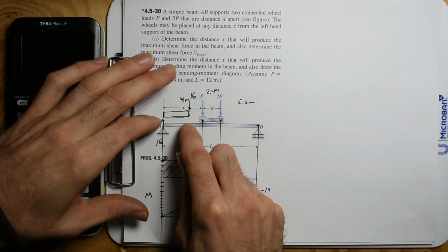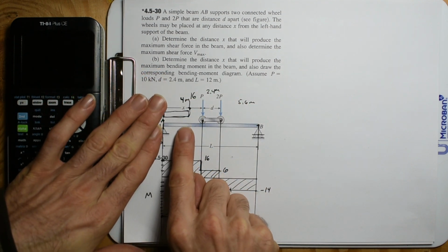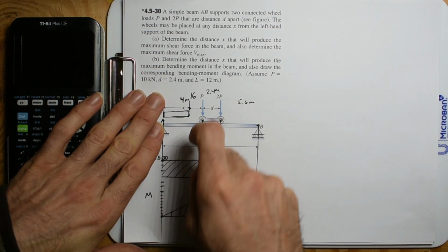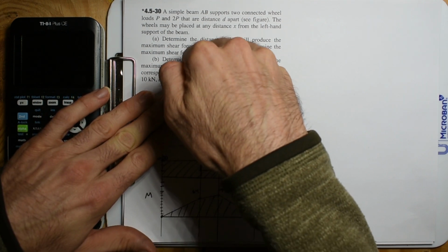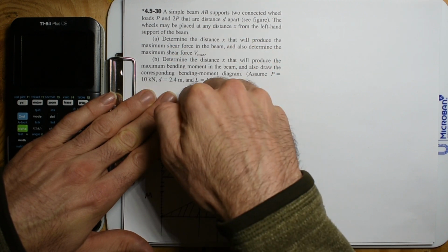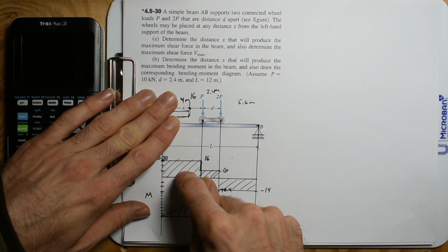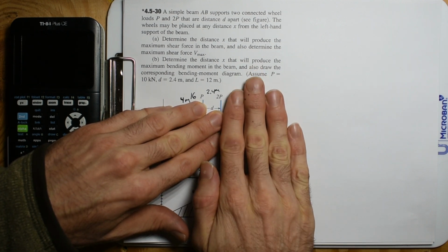If we do cut this chunk out, all the weight is over here, and we do have an upward force holding this chunk, but we are going to have a downward force shearing it in this direction, and that's going to be the positive direction. That's why we have positive shear. But when we get over here, we must have a shearing force in the upward direction.